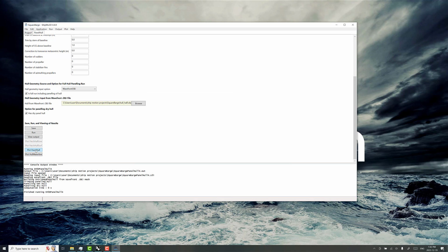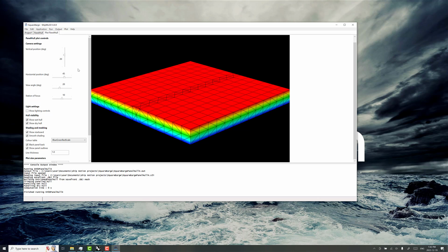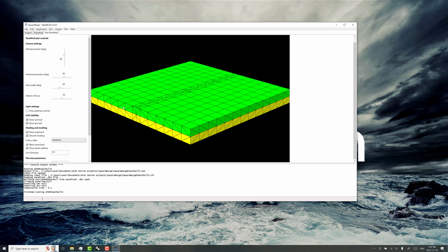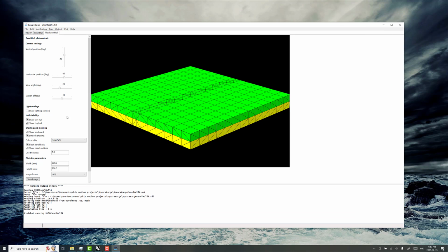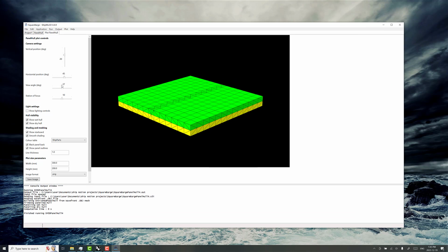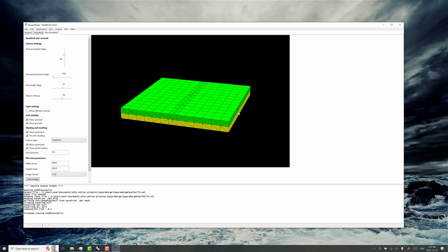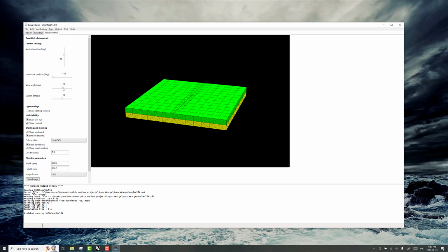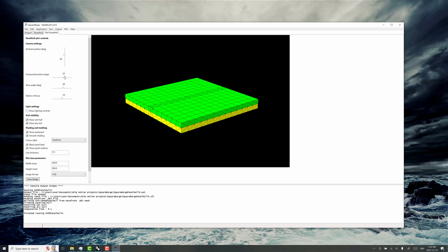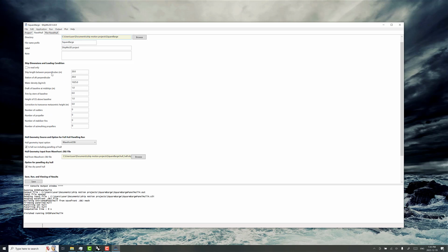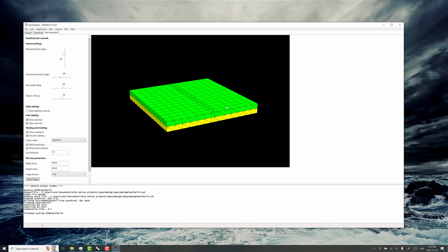It looks like it's run successfully, and when we plot the panel hull, it's showing the mirror imaged portion there as well. I like the ship parts color view here because it shows the dry and the wet hull really nicely. Just adjust the view angle there. Note also that Shipmo3D will automatically refine the mesh around the waterline for you. That helps significantly with the quality of the hydrodynamics calculations. And if you change the displacement values in here or the trim, you'll see a different wetted hull area. Just beware that you'll have to go through the calculation process, which we'll show in another step shortly.